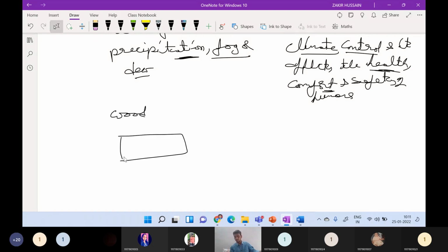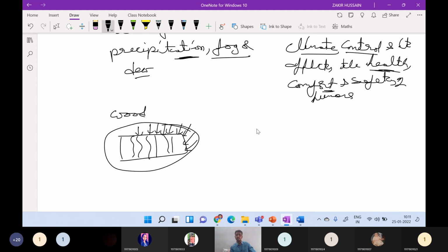Inside the home, if some wood material is there, what happens due to excess humidity? A large amount of humidity means water vapor will attack the surrounding wood, forming molds and deteriorating the wood material. In the same example, if the humidity is very low, then without humidity this wood material will crack because there is no surrounding moisture.